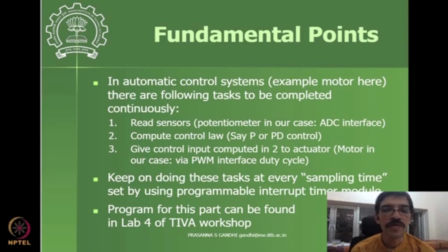So for example, if you have written a PWM program, you need to see which parts of that PWM program can go in the main program, and which parts should come in the interrupt service routine. You can bifurcate. For example, you just want the PWM duty to be changed here, so all other commands or registers in the PWM routine should not change.